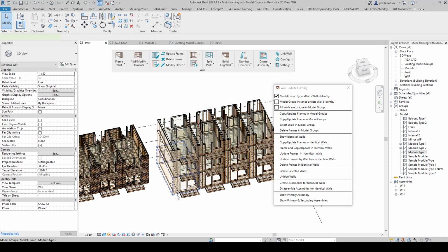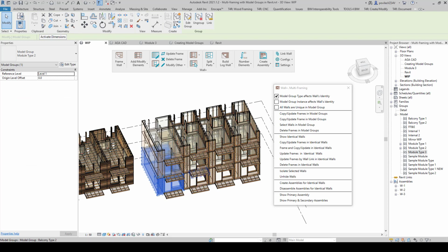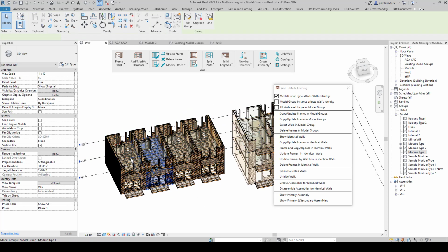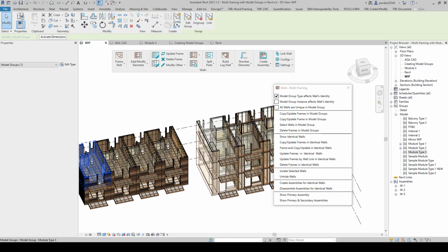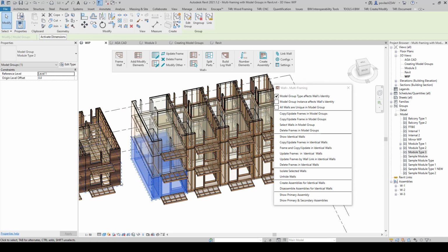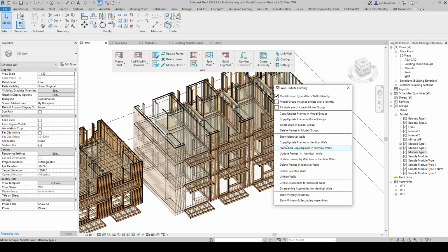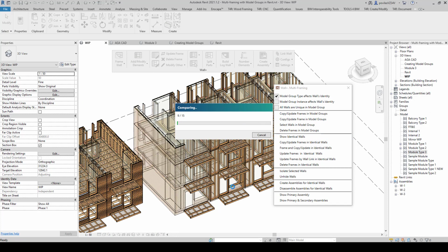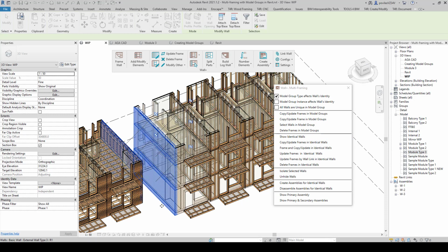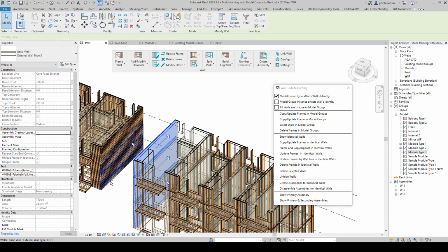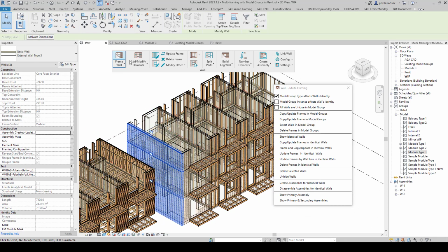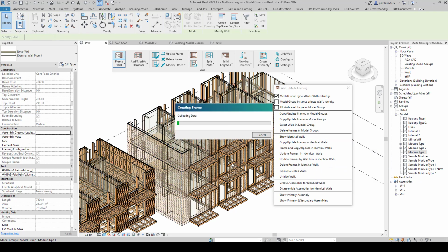So that's the breakdown of what has happened with our wall frames, and that's already there. It didn't take too long, and we have those done. I believe this one is model group 2, and that's our model group 3. So that's kind of done already. Model group 2: we can also do it by filtering out the walls and framing them separately. If we want to do that, you can use native Revit tools, just deselect 3 walls.